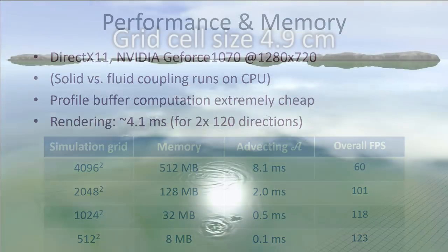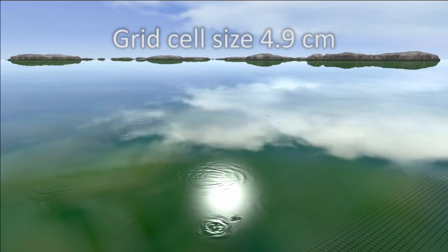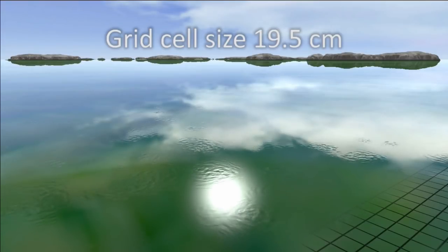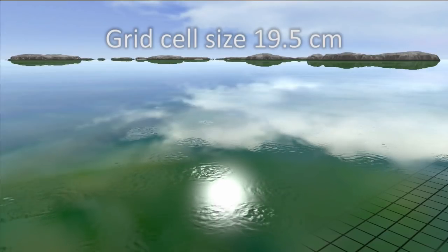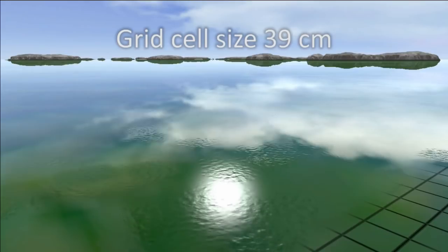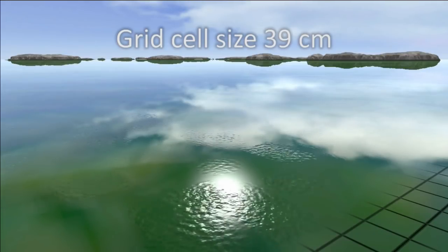To illustrate what happens if we reduce the grid size, here's a raindrop example where on the lower right I showed the grid this is running on. This looks kind of okay. But if I increase the grid cell size, you see that the initial impacts rather become little patches here, because we cannot simulate anything that is smaller than the grid cell size, right? And if I further make them bigger, then you see now it looks rather like patches. So this is clearly the way it works here.